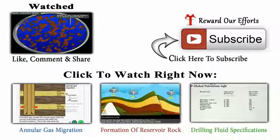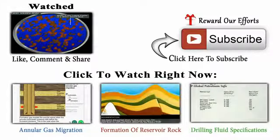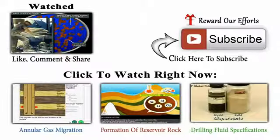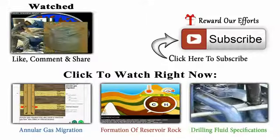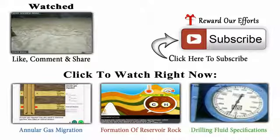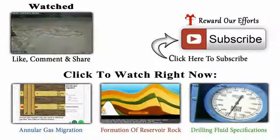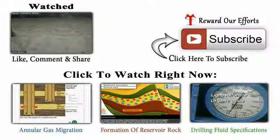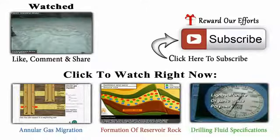Water makes up the liquid part, or phase, of a water-based mud. Crew members put clay and special additives into the water to make a mud with the properties needed to do its job well. For example, clays give it thickness, or viscosity. The water in the mud may be fresh water, seawater, or concentrated brine, salt water.